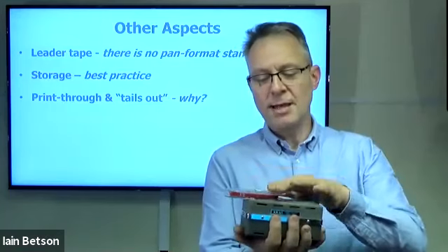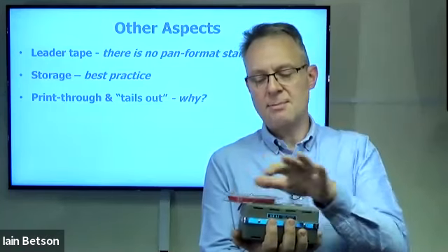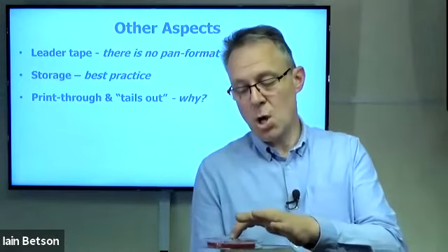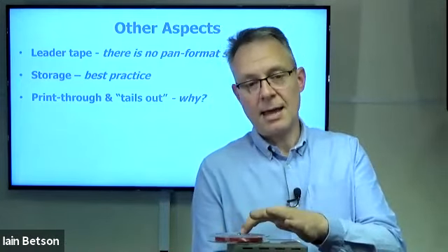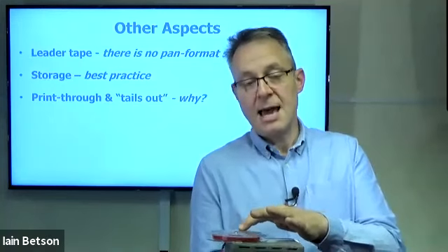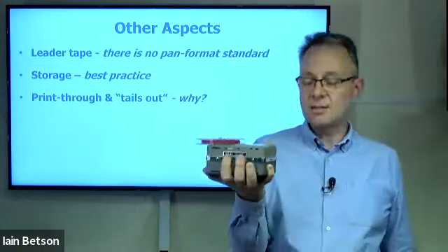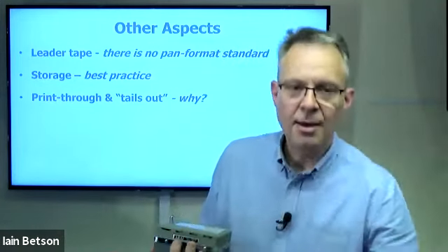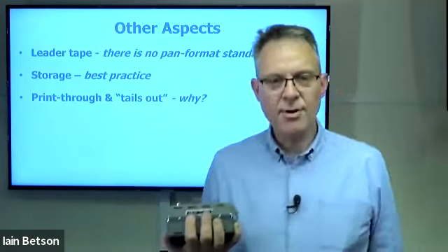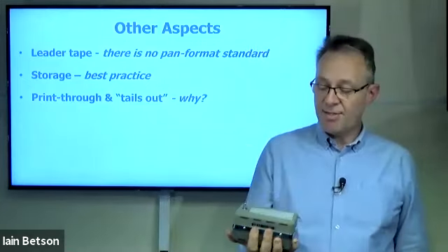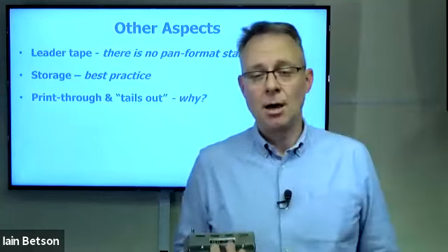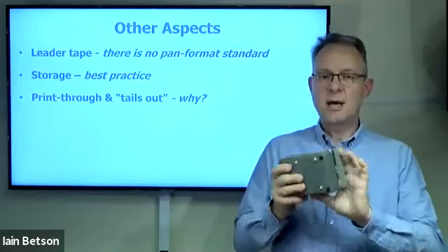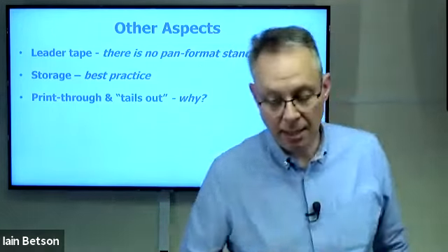You put the tape on the reel and you slowly rotate the tape around, and it'll take 10.5-inch reels with the appropriate hub. You just slowly turn it around, maybe 2 or 3 passes, and it will basically obliterate anything that's on the recorded tape. Obviously, don't do it next to your Beach Boys tapes or any of your pre-recorded stuff. And the other thing is, if you've got a pacemaker or any other electrical gizmos in your body, I would consider whether you want to use a demagger.